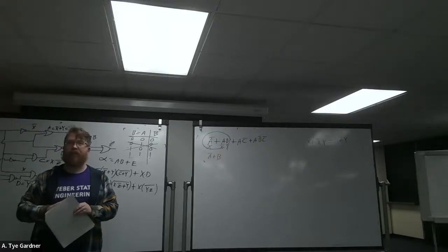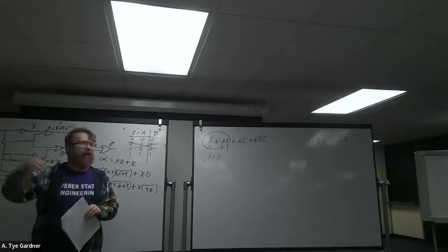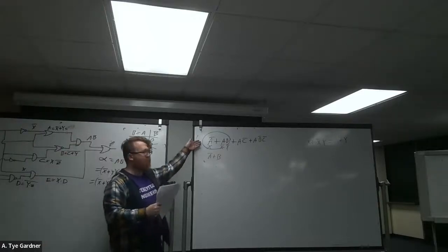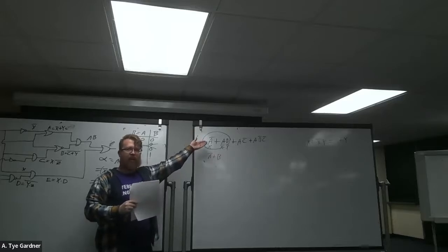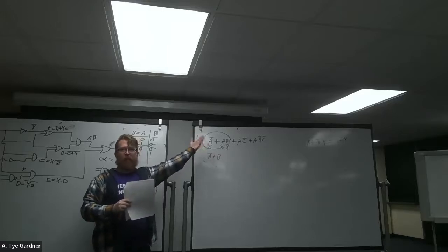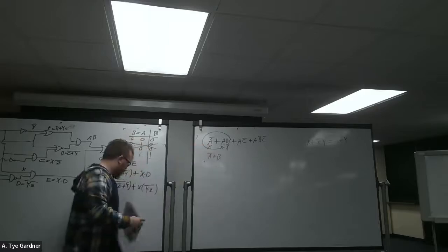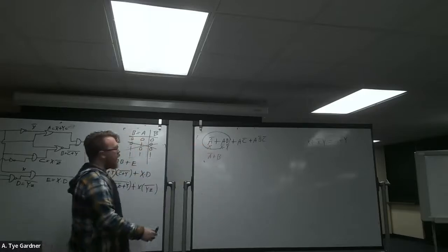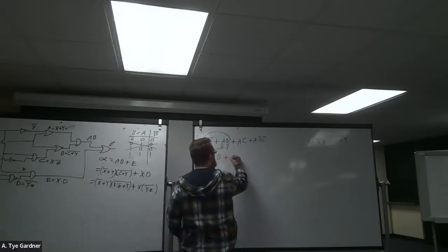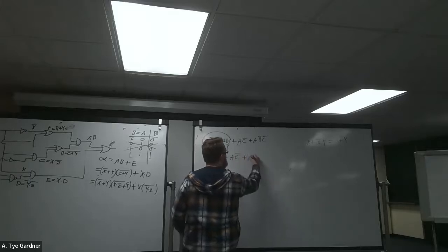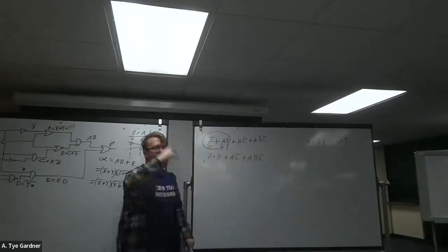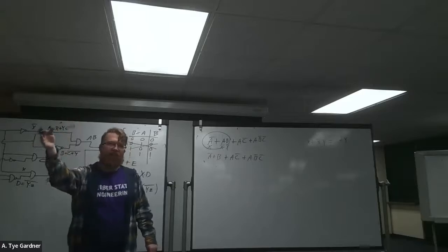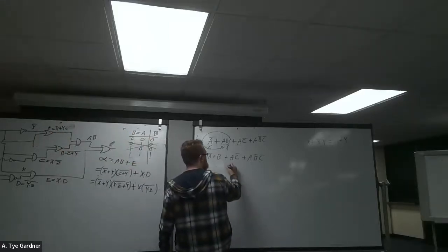Does everyone see that one? That rule, it helps. Every time I use this, I write it out like this if the variables are anything besides exactly what they are, because this is very easy to mess up. Okay, now I have that, and now I have A C bar or A B bar C bar, and now I can do the clever suggestion, which is factor out the C bar.